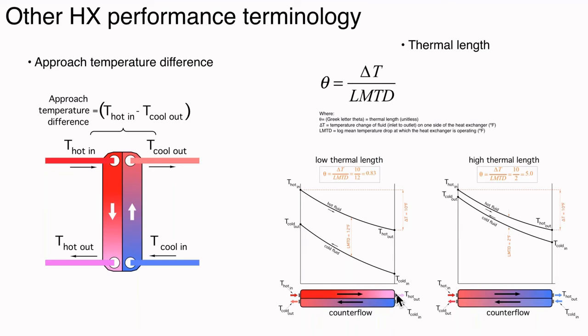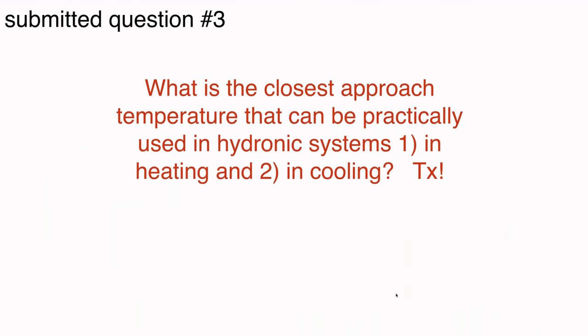And also, in a case of flat plate collectors, usually it's a longer plate rather than a shorter plate because of the ratio of the temperature change of the fluid divided by the available log mean temperature difference to create that rate of heat transfer. So again, you can put specific numbers into these formulas and calculate these out, but I put them in just so the terminology is explained here.